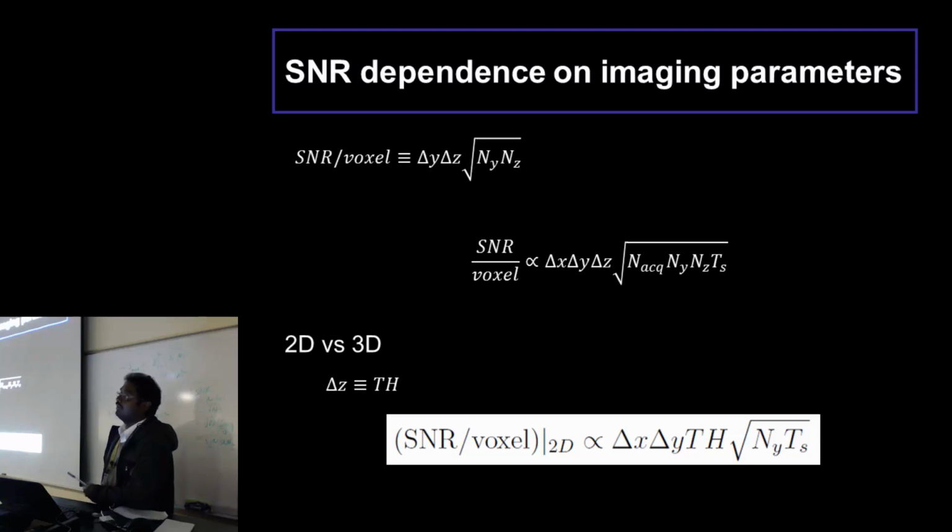So you can aim to get to square root 2, then you will know, okay, what other parameter can I keep constant and change the other one to not have half worse but square root 2 worse only. Or if you want to keep this SNR the same, then you can figure it out anyway. So all of these combinations is what I'm talking about. This expression would be useful for you.